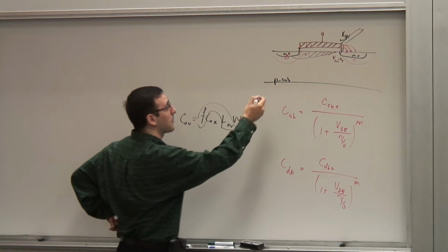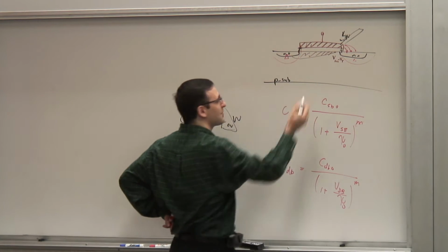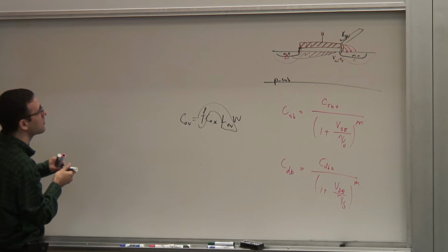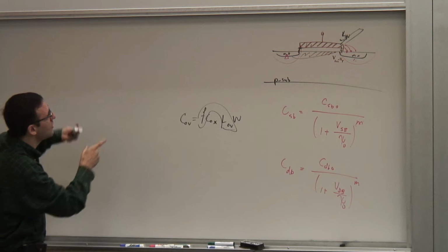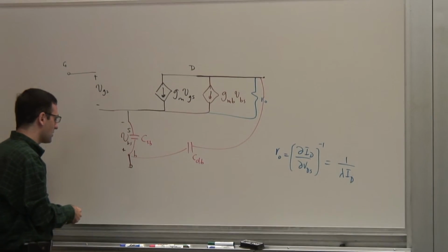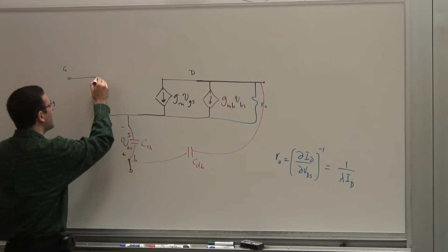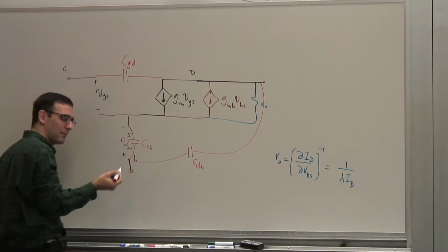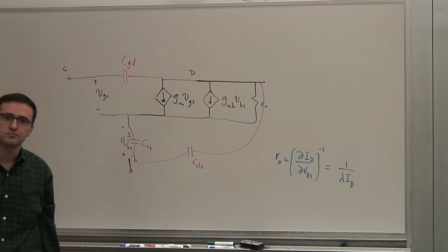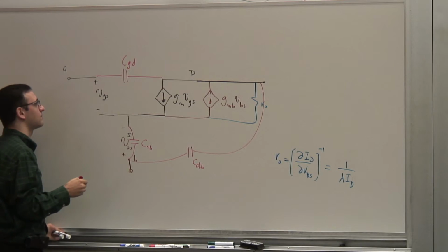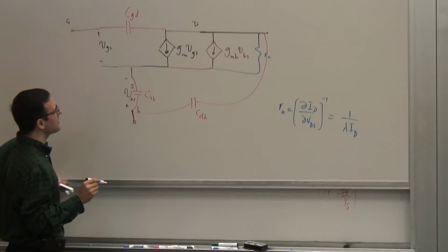So we have two overlap capacitors. We have a similar one on this side because this is a symmetric device, right? You can switch the order of the gate and drain and gate and source. So I have these two capacitors. Let's talk about the drain-gate one first. There's a capacitance Cgd, which in the pinch-off region is the overlap capacitance. And I have a similar one between the gate and the source. But let's talk about that capacitor.